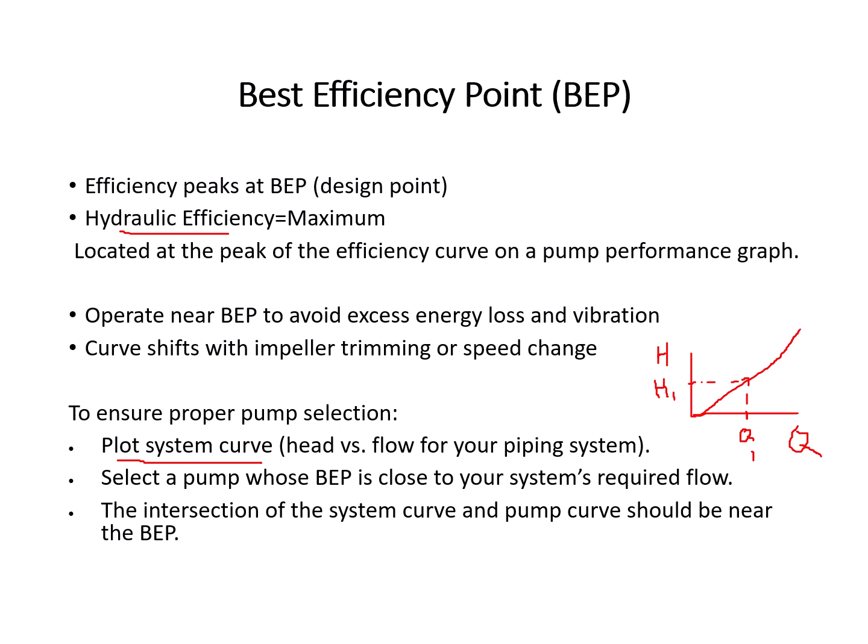The intersection of the system curve and the pump curve should be near the best efficiency point. Like this is the pump curve. This is the system curve.